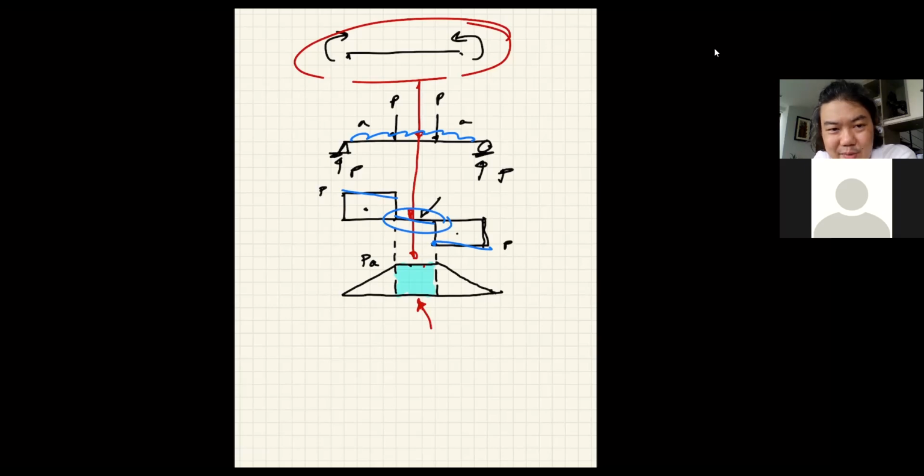We can neglect so many things. Just like the truss, right? I talk about the truss. Two force member. So where's the weight of the truss? We neglect it. It's there, but we neglect it. So in a truss, there's always moment in your truss member due to the self weight, but it's small enough that we can say, I didn't see it. Thank you for your answer. Sure. And I'm saying this because this is real. This is what we do.